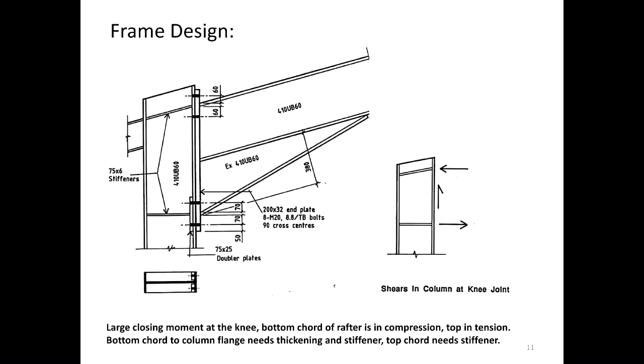We then provide stiffeners. So that's the stiffeners there. And then the shear force usually is taken up by the bolts. And these bolts have got very, very high capacity in shear. So having 8 bolts at the knee usually is enough. You saw the big bolt I brought last time? That was from a knee connection site we went to 2 years ago. It's very, very big. So hopefully when we go, you'll see most of these on sites.